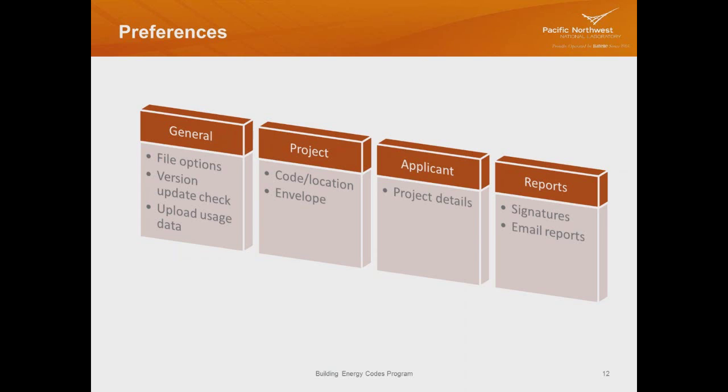And then you can actually email these compliance reports right from within the tool. And that feature works in the desktop version and it works in the web version. So both of those have that feature, and you might want to put your email in there only once. So if you're going to become a heavy user of REScheck, under Preferences at the top, the menu, you can put your email in there and then it'll automatically populate that feature where you don't have to type your email in every time.